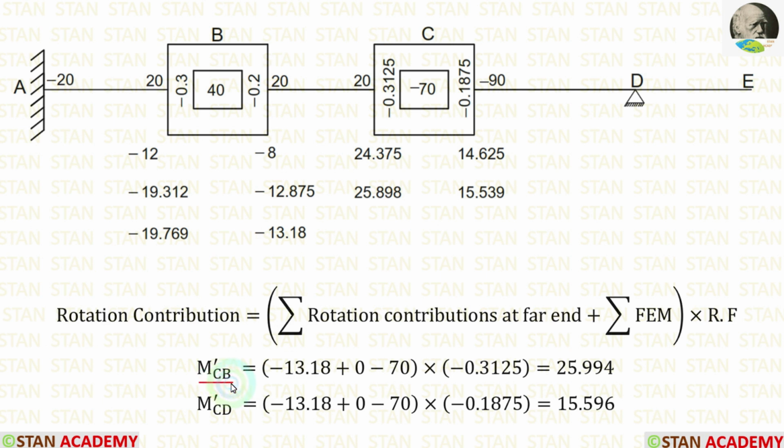Now let us calculate m dash CB. The latest rotation contribution in the point B is minus 13.18. The rotation contribution in the point D is 0. So for the summation of rotation contributions at the far end, we are having minus 13.18 plus 0. The summation of fixed end moment is minus 70. The rotation factor for CB is minus 0.3125.